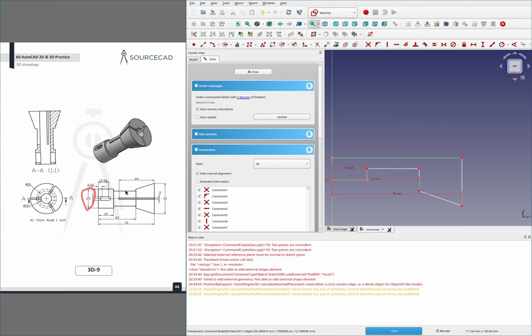And then this bit here, let's see, I guess they're dimensioning to hidden lines again. It is this thing here, I believe, because it might have been this outside one, but you can see on this set of hidden lines right here that they actually go out to this outside one. So this outside hidden line is actually this section here that you just can't see because it's hidden behind the kind of tail feather part of this.